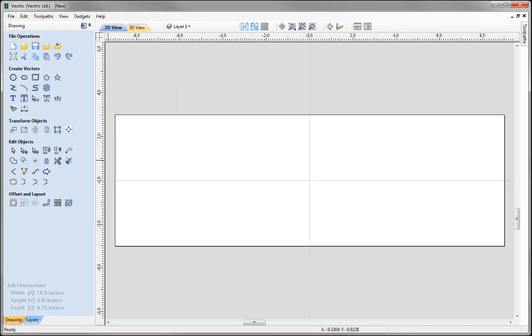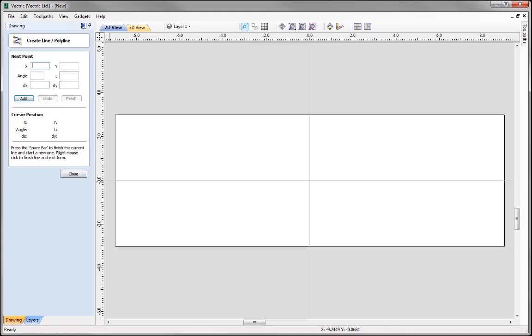And one final adjustment is I'm just going to turn off smart snapping. The reason for that is I am drawing up organic shapes, so there isn't really a need to have the smart snapping feature switched on. I'll still keep the geometry snapping on, as that will enable me to still be able to snap to centres, midpoints, things like that, which I may find useful. So now we're ready to begin drawing. So let's go into the polyline tool.